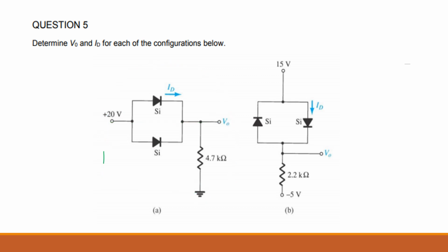So you have 20 volts, and then what is happening? Yes, so you have a 0.7. So is it 0.7 or 1.4? Why is that? It's in parallel, yes. So you need to understand them. Both are parallel to each other, and this one should be 20 minus 0.7, isn't it? Because you have just a 0.7 drop. If they are in series, then you have to add them together. It will be 1.4, if two of them are in series in the forward bias direction, both.